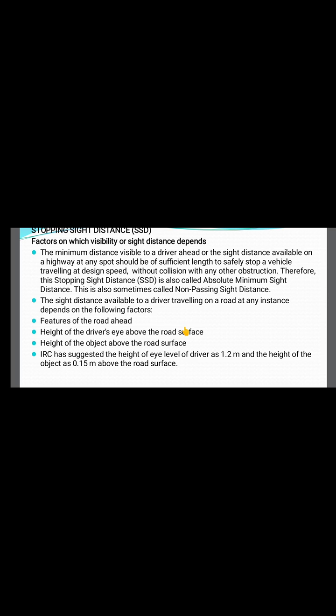So that is also one factor: the height of the driver's eye above the road also comes into the picture here. The height of the object above the road surface is the same case. IRC has suggested the eye level of the driver as 1.2 meter and the height of the object as 0.15 meter above the road surface.